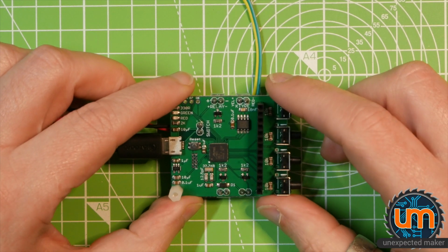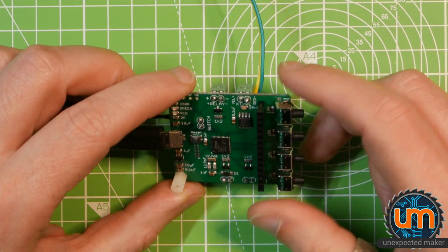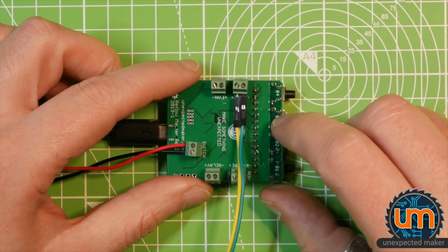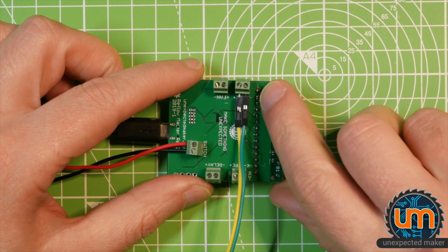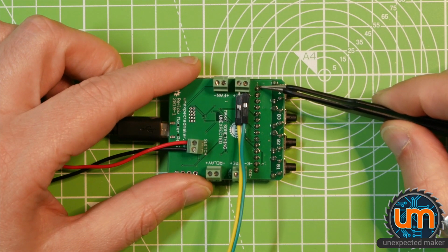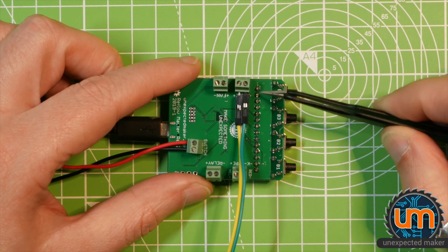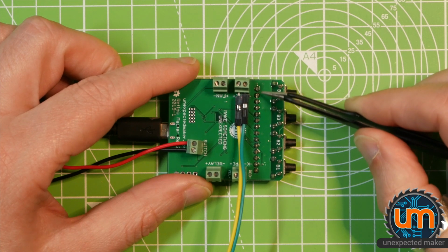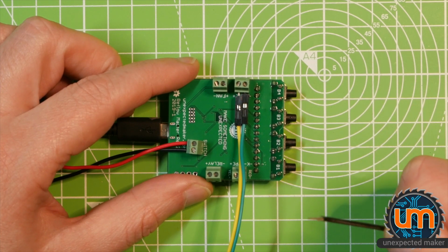Okay, so we're back. So clearly there's some noise on the line. Let's do something about it, shall we? It's going to be as simple as just sticking a cap for now across these 2 pins. So this pin here is the 5 volt line of the TFT, and this is ground. Very convenient. So I'm going to grab an 0603 10 microfarad cap and just solder that, wedge it into place right now, just to try it and see if it fixes the problem.